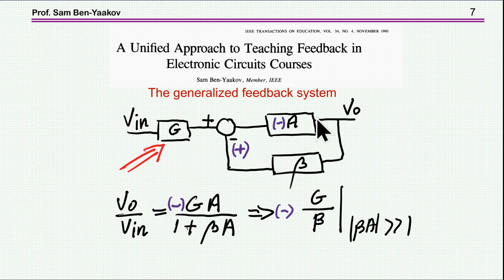So if we have a G block here, a gain block or transfer function block, then we're going to have the regular feedback transfer function, which is A over 1 plus beta A, times G, because G is sort of multiplying everything. Now when beta A is much larger than 1, and this is in the useful range of operation, we see that the gain becomes G over beta.